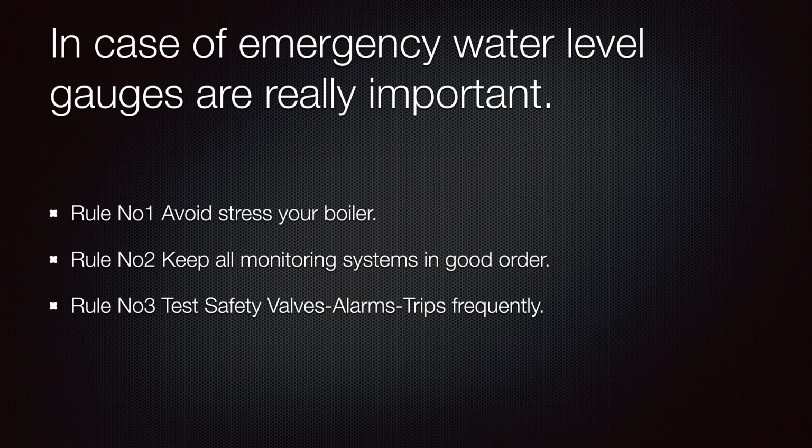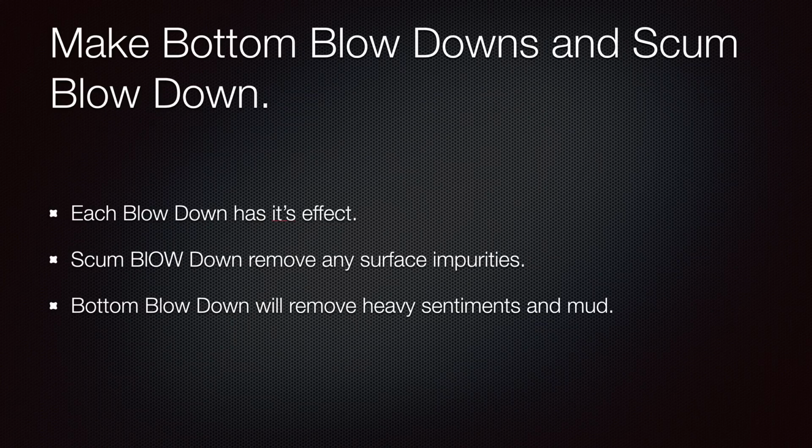So let's move on to another topic. Make blowdowns, bottom blowdowns, and scum blowdowns. There are bottom blowdowns and top blowdowns, and each blowdown has its effect. The scum blowdown, which is the top, removes any surface impurities, and the bottom blowdown will remove heavy sediments and mud. This is the reason why we make them.